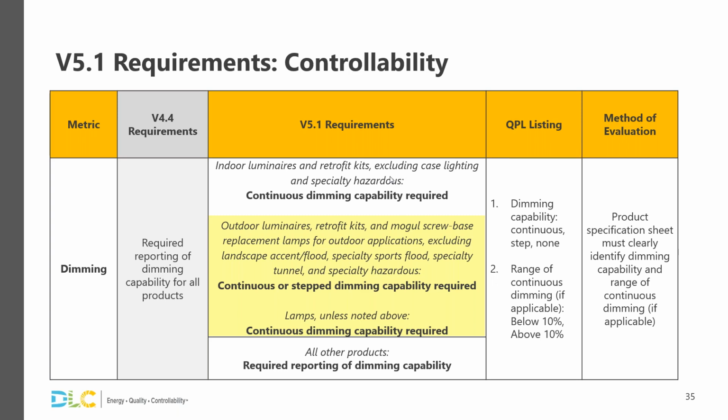TLEDs could achieve dimming through a wireless signal, so either coming from a wireless wall dimmer or something like a wireless daylight photocell sending a signal to the lamp to dim. Type C drivers, of course, many of them already are dimmable, and a TLED could even achieve dimming through phase cut. Okay, thanks, Dan.